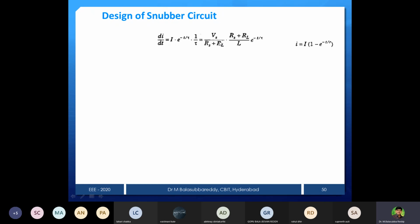Now I know I is Vs by Rs plus RL into e power minus t by tau. So 1 by tau is there. You can represent it in this fashion and automatically these two will get cancelled out, this one and this one, and finally di by dt is equal to Vs by L into e power minus t by tau.